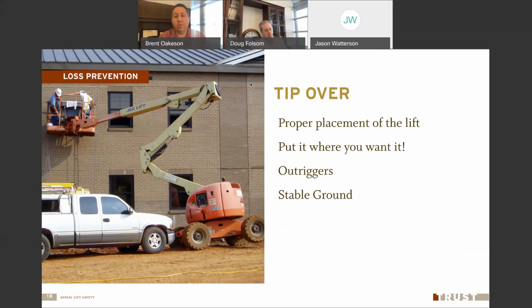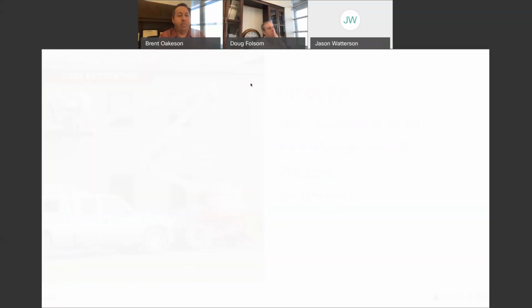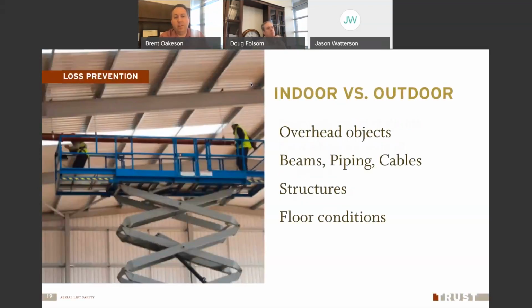So put the lift where you want it. Make it easy on yourself, even if it takes a little bit of time. Get it in a good spot before you go up in the air. There is a little difference between working with lifts indoors versus outdoors. One of the things you might encounter is overhead objects.